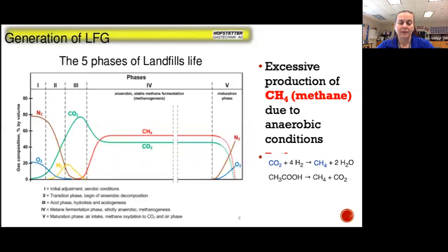And then the landfill itself will actually generate gas. At the very beginning, as a landfill is being created, we have aerobic decomposition, meaning decomposition in the presence of oxygen. And that decomposition is going to generate carbon dioxide. This is a short phase, not a significant contributor to CO2, although it is somewhat a contributor of carbon dioxide.